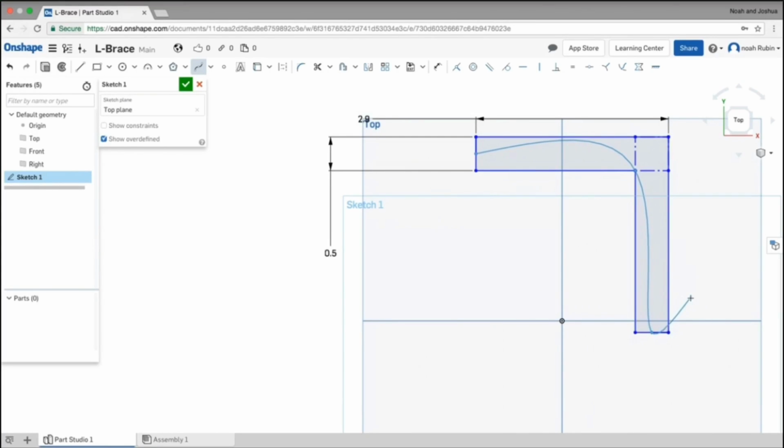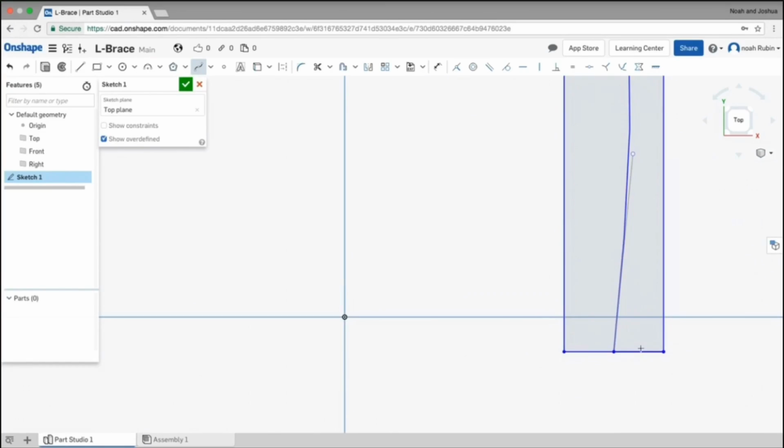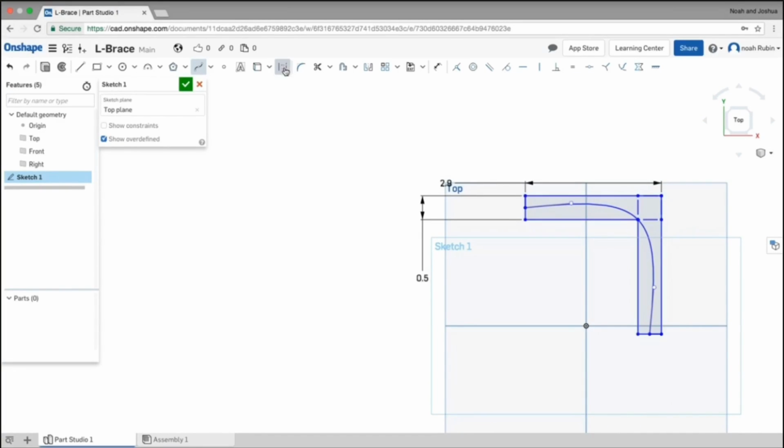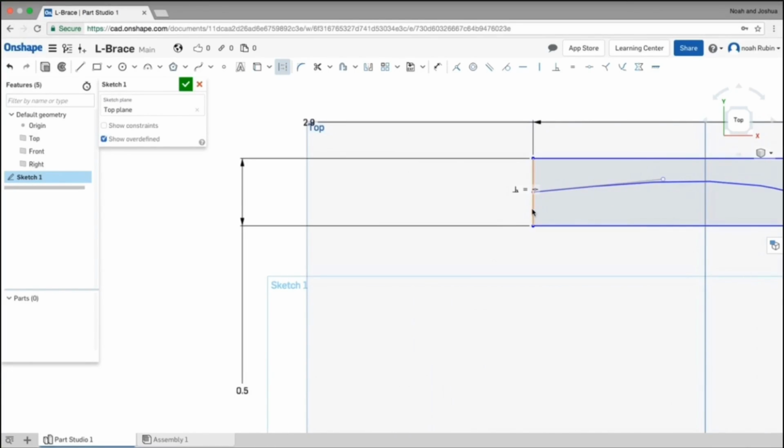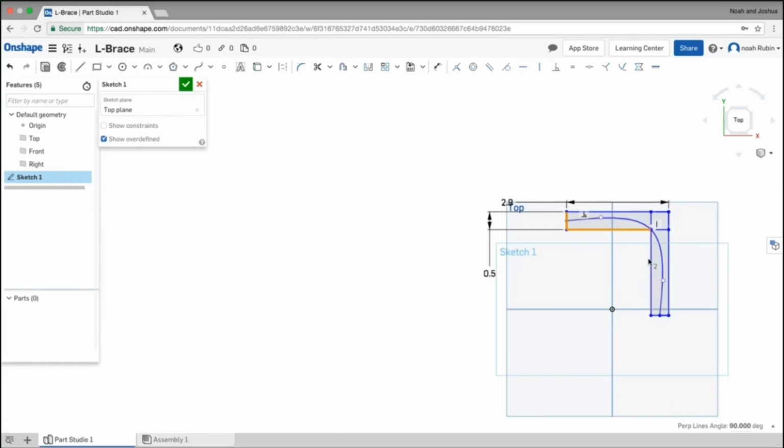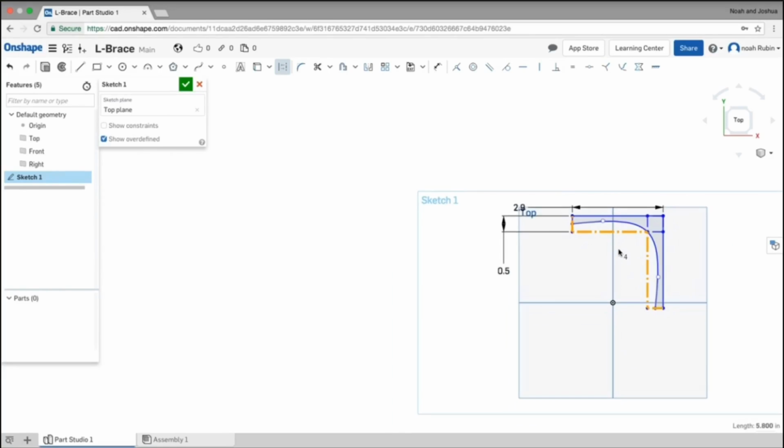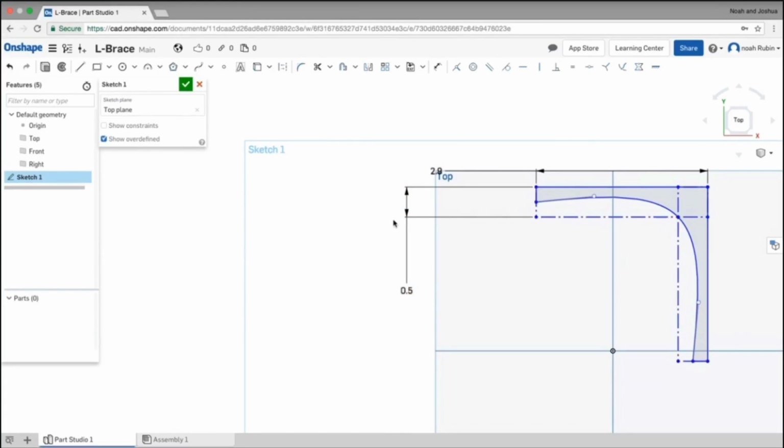And now we're left with substance in this area here. See how we have stuff there? And now we can use the construction tool to just click on the areas that we want to be construction lines. So that, and that. And then we press Q, and it goes to construction, and you can press escape, and you can see that now we are left with a much nicer shape. But still, again, here at NJ Printing, we're not going to stop there necessarily. We can keep going.